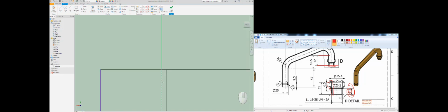So I made a mistake at this point. I'm just going to correct it. This time I have this line, this side here is 1.5. We have a very thin side. For this thin side, I will make another step at this point, starting from 9.5 millimeters, and I will connect this one and make the trims for unnecessary parts.